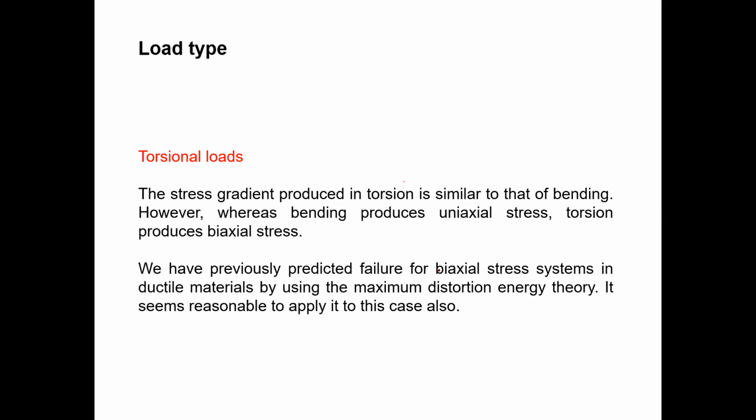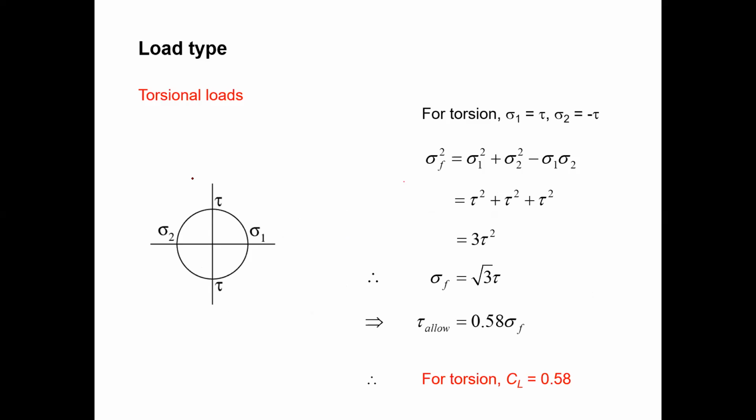What I need to explain is, if you remember distortion energy theory, we need to eliminate the torsional load, I mean shear stresses, and produce the principal stress loading pattern. This theory we will use later on to calculate this kind of thing. If you use this equation, this is the DE theory, distortion energy theory.